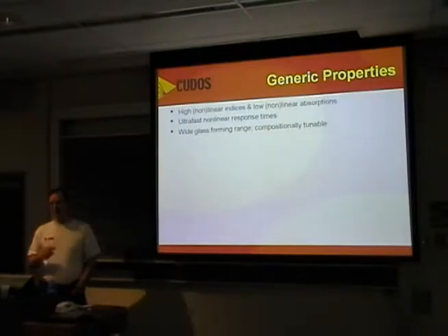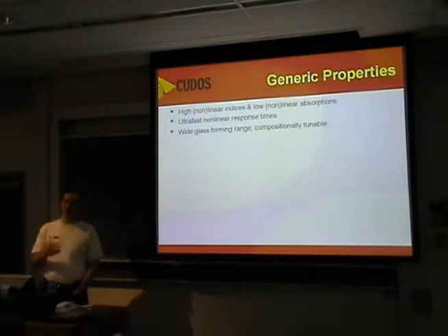Importantly, these materials, because they're made up of just a mix of different elements, have quite large glass forming ranges, and hence you can actually tune the composition and tune the behaviour of the material. That's important if you want to make, for example, buried channel waveguides where you need a core and a cladding material.